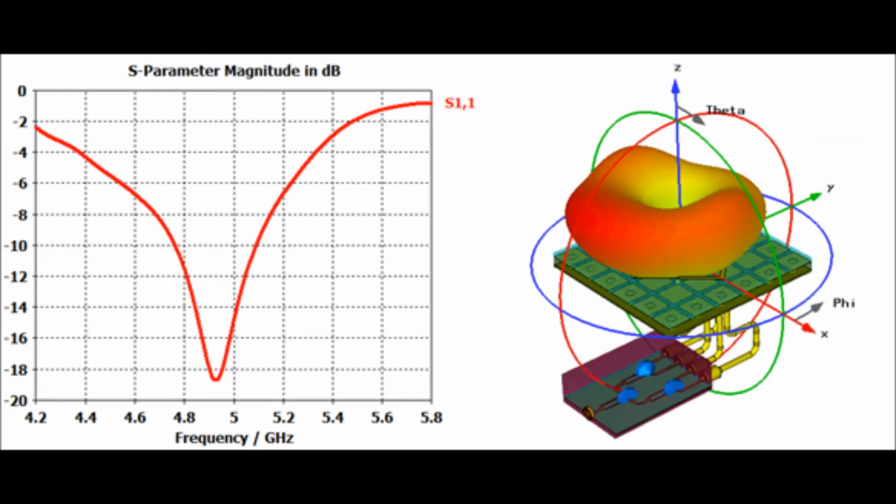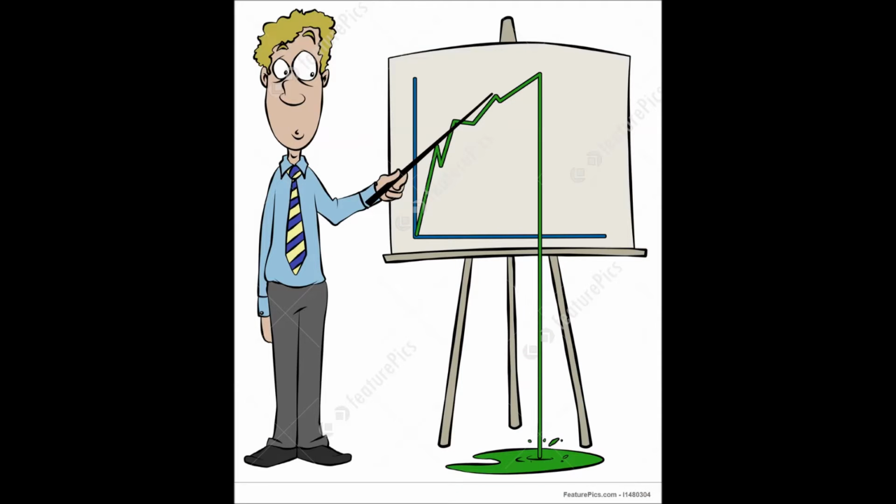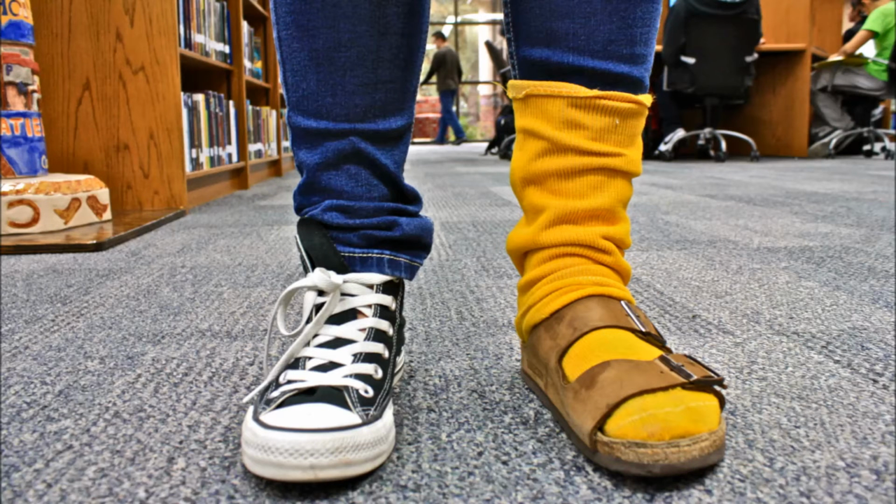Mathematically speaking, it is a logarithmic ratio which is measured in decibels, and it compares the power reflected by the antenna to the power which is being fed into the antenna from the transmission line. Any reflected power from the antenna will be at least some decibels below the input power. This drop in decibels is basically the return loss ratio, and it will increase considerably if the antenna is mismatched.